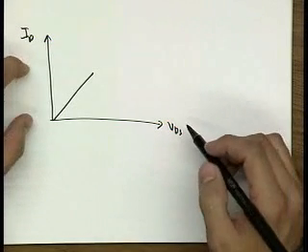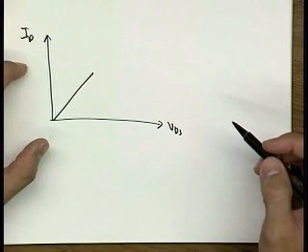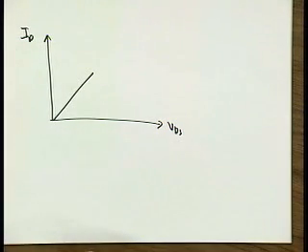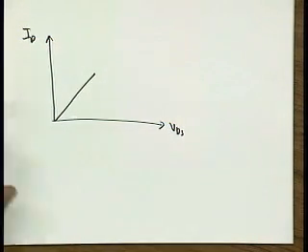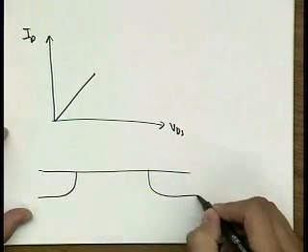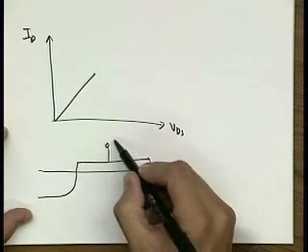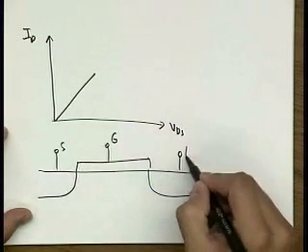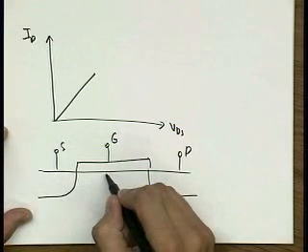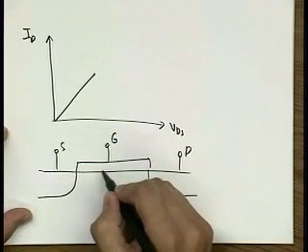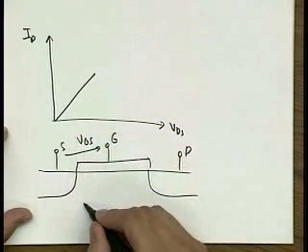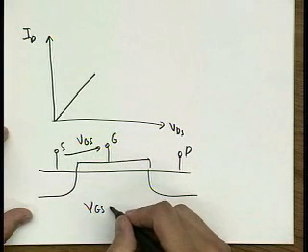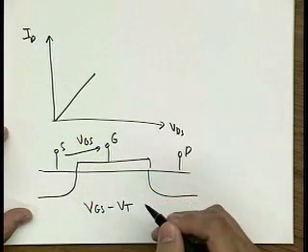So now if we keep increasing this drain and source voltage, then what's going to happen is we are going to enter a saturation region where you basically can no longer assume that the potential across your channel, so if you have your gate and source, so drain, so you can no longer assume that you have your channel potential here VGS minus VT.